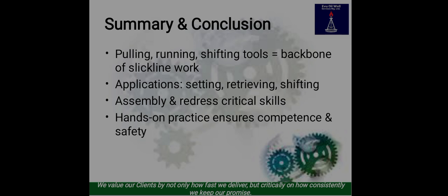Now, the mitigation strategies, which I would highly recommend for you. To prevent recurrence, I always recommend these measures to young operators, even the supervisors. Develop and use a pre-job checklist covering tool verification, sleeve confirmation, and surface function tests.